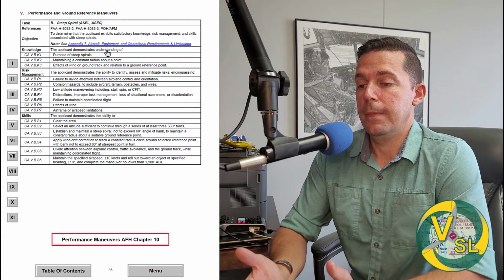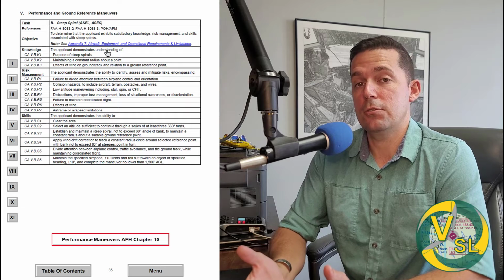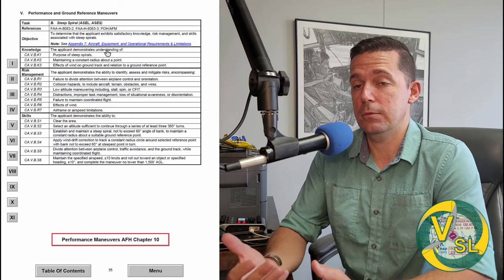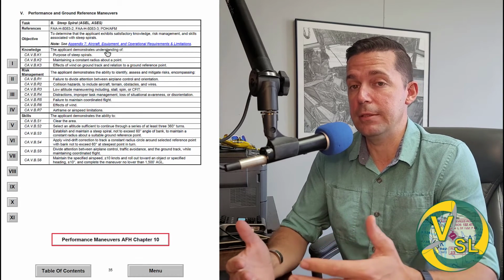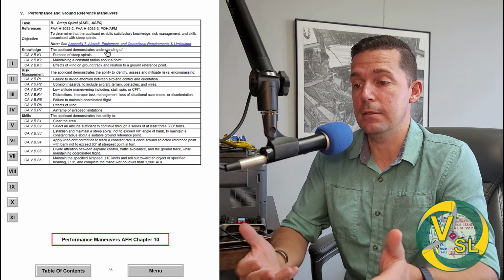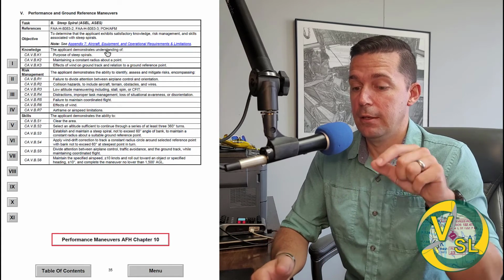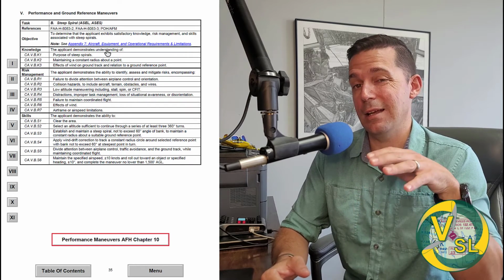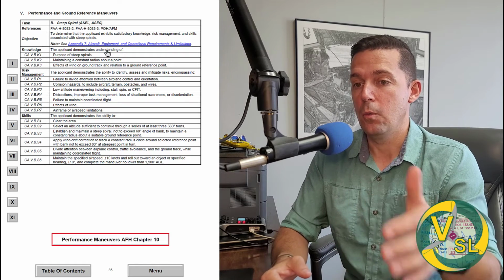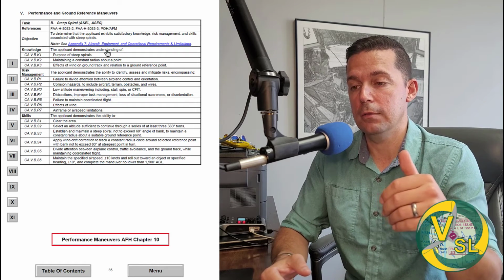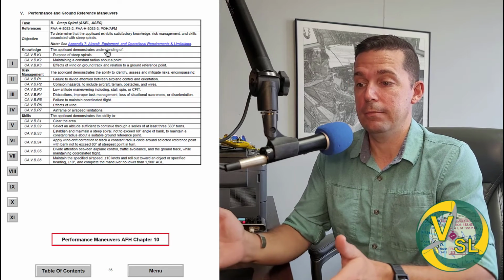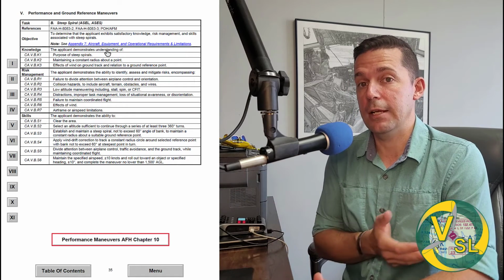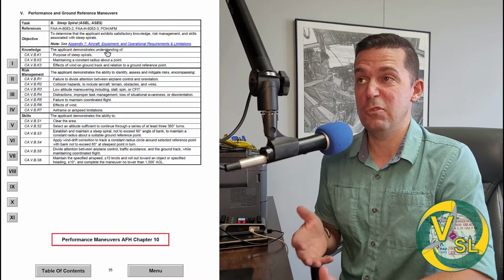So the goal of this maneuver, it's not some sort of circus trick that we're asking you to do to show mastery of the aircraft. I mean, it is that. We're seeing that you have mastery of the aircraft by being able to complete the maneuver. But what it's really about is your ability to fly to a landing point, spiral down over that, and then effect a landing on that landing point. So a lot of times I'll combine this maneuver, the steep spiral, with a power off landing to either a simulated power off landing in a field where we'll abort at around 500 or 600 feet, or to an actual runway. We have some kind of non-busy airports here.